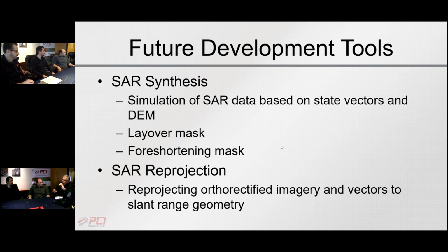Persistent scattering wants you to process all the permutations of all the interferograms, identify the highly coherent points, take the trend, and then use that to correct for atmospheric effects. We basically have put it on the user to identify the areas that they figure are stable, because we anticipate that in an operational setting, most people will know the areas that are stable anyway. So we just cut that part out, but we will get around to it.